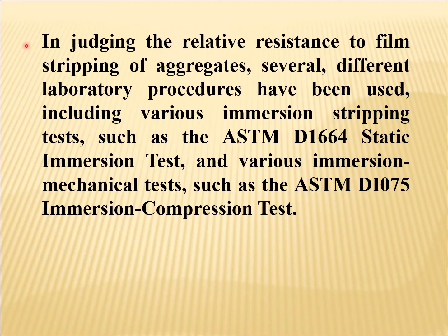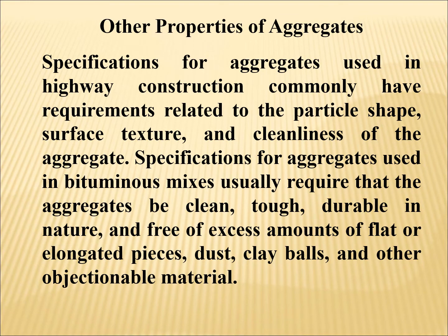In judging the relative resistance to film stripping of aggregates, several different laboratory procedures have been used, including various immersion stripping tests such as the ASTM D1664 static immersion test and various immersion mechanical tests such as the ASTM D1075 immersion compression test. Now, some other properties of aggregates.